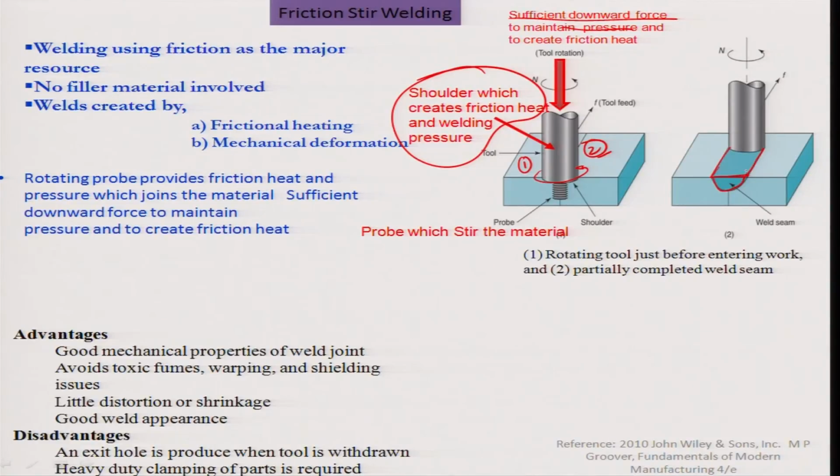Okay. The material really does not melt in this area, but because of friction and the pulling forces generated between both the materials, there is an overlap between the materials, and that creates a weldment as such between both the sheets.